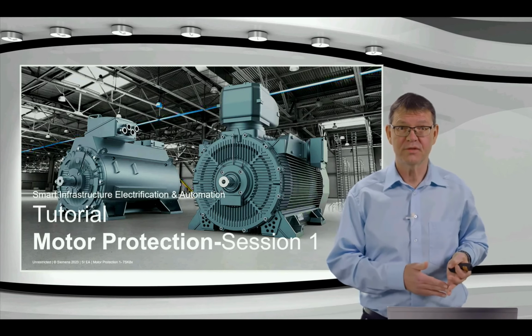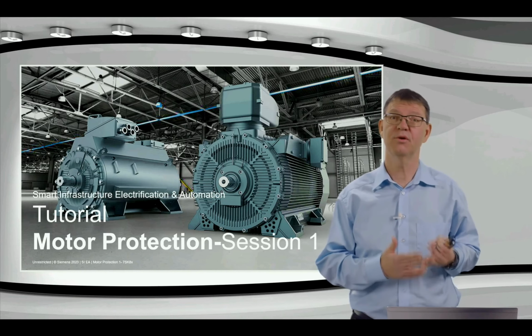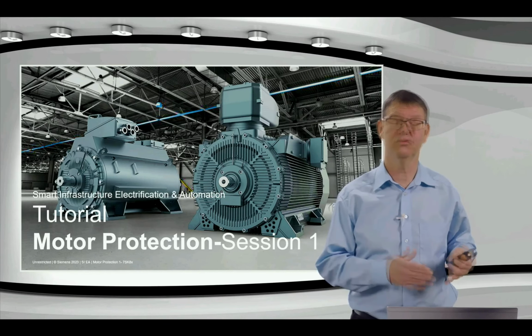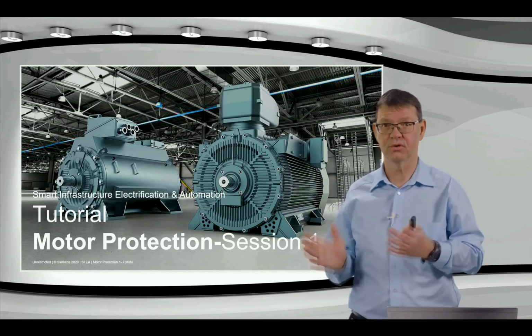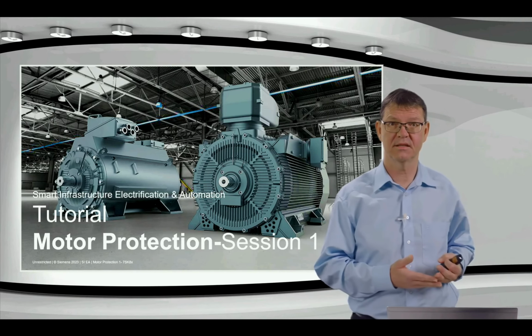In the third part of today's tutorial, we explain the thermal model, which is the basis for our thermal overload protection function for the stator and also for the rotor, and explore the features of these functions and its settings.